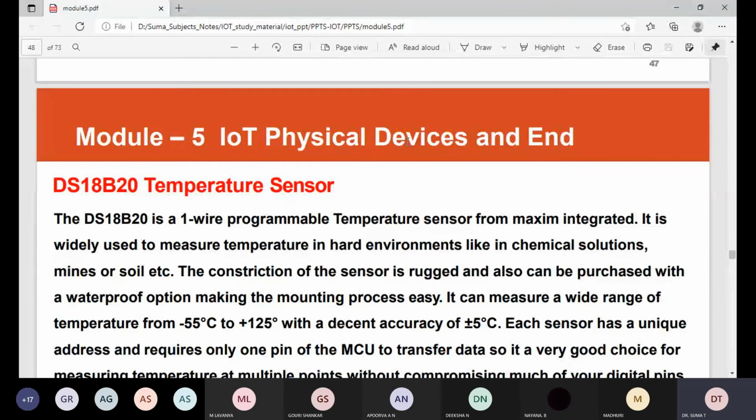This example shows how to get an analog input from the general purpose input output pins and process the input. An infinite loop runs over the sensor which records the intensity of the light with the date and time stamps every second. Compile the code given below and upload it to the Arduino UNO board to observe the desired output.